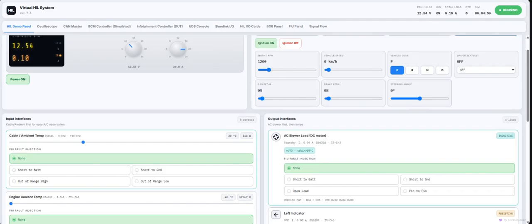Whenever a person goes to a control desk or experiment environment bench, he or she will be facing these kinds of panels or parameters, where based on the test case, he or she has to change the engine RPM value, change the temperature sensor value, then observe the output. So these are the kinds of scenarios we are targeting, or studying, here on this HIL bench.